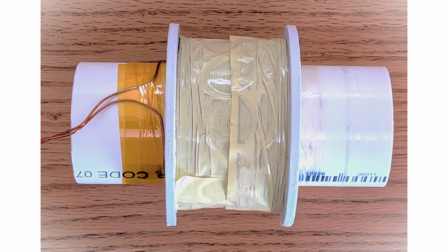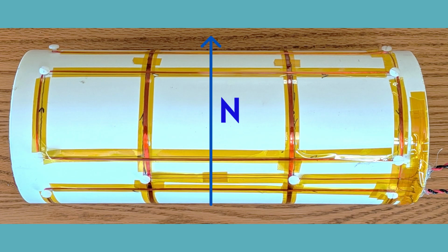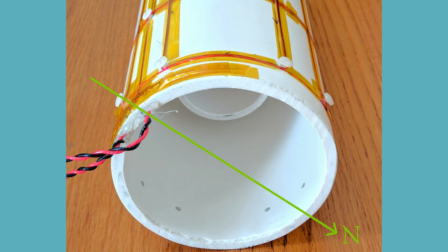The polarization and read coil is 600 turns of 18 AWG magnet wire on a 2-inch form. The gradient coils are on a 4-inch form. The tube is aligned perpendicular to magnetic north. The gradient coil rotation is aligned to the magnetic north direction, which points down.